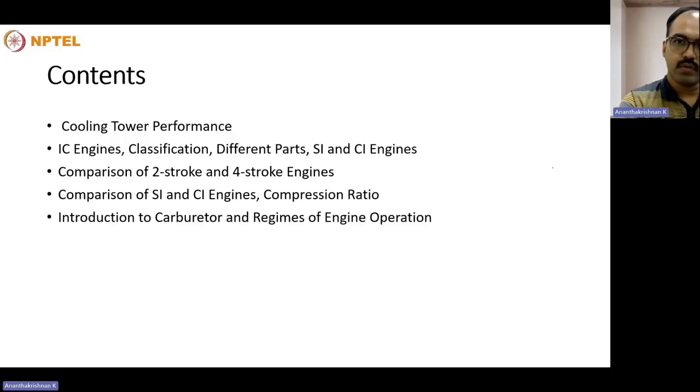Since the cooling water takes the heat, it will get heated up. Its temperature will rise, but at the same time, we do not have infinite resources of water, right? So we have to circulate it, and to operate it in a loop, we have to cool this water. That should be done by using an evaporative cooling device. So a cooling tower is one such where the water will be cooled by the ambient air, where the water temperature can approach the incoming air's wet bulb temperature.